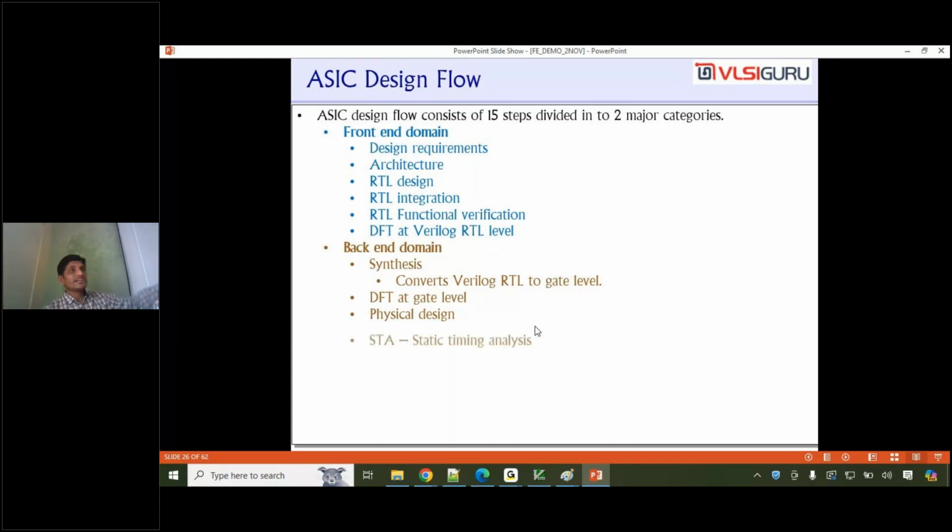While doing that, they do something called static timing analysis. If static timing analysis is not done properly, the electronic device won't work. I mean, you cannot even open this because it will go into an unstable state. Once it is done, the next step is called custom layout. The next will be physical verification.